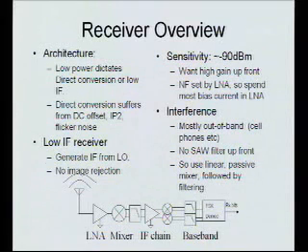But there are a couple of problems with low IF. One is I have to generate an IF signal now for my oscillators. That's actually fairly easy. I can just divide down my LO, which I'm doing anyway, and just pick off that divided signal and use that as my IF. The other problem is that you have to supply image rejection. And my answer to that was to not supply image rejection.